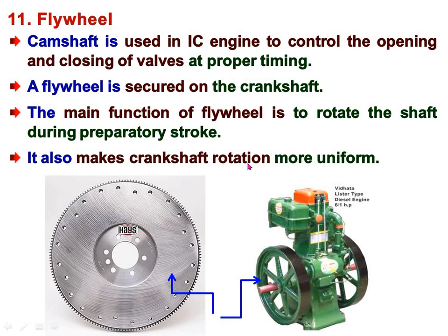It also makes crankshaft rotation more uniform. Due to the explosion of the burnt gases, there will be production of shock load, and the piston will reciprocate at higher RPM. So there will be shock load on the piston, connecting rod and crankshaft, but whatever extra power has been produced by the engine has been stored in the flywheel, and it smoothens the power. So the crankshaft rotates